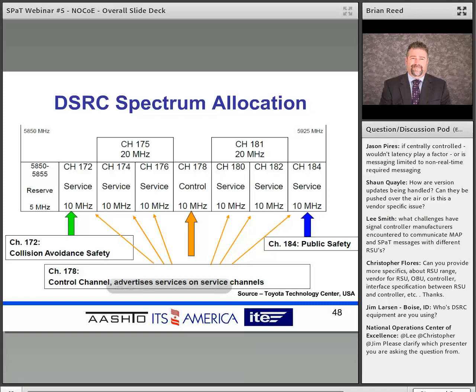So we talked a little bit about channelization and effectively how these are broken out or set up for RSU deployments. Most folks at this point are setting up RSUs, and as part of that initial setup implementation by site, you may be looking at certain site-specific applications, as an example, like transit signal priority or signal phase and timing with the map messages, WSA broadcast, and each of those pieces or application sets would be used on specific channels.